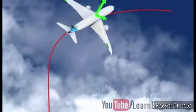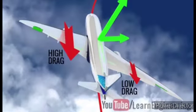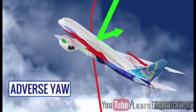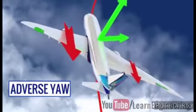This way, the pilot can make a turn of any radius depending upon the angle of roll and the speed of the airplane. However, this banking technique has some drawbacks. When you keep one aileron up and the other aileron down, the drag forces induced on the wings are not the same. This will cause the airplane to yaw. This phenomenon is known as adverse yaw. The rudder has to be operated simultaneously to prevent the adverse yaw.